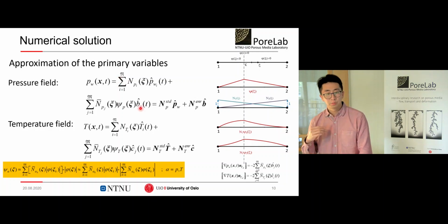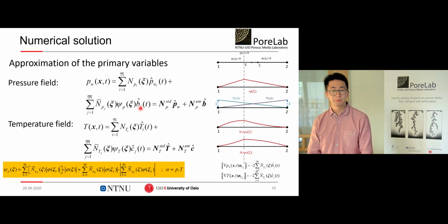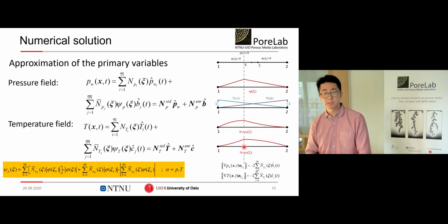So to approximate this, we need to add a continuous function with a discontinuous gradient. Here we use this modified level set function, as we see here, and the last two figures are for this enrichment function. And the same as the displacement field part, the enrichment function will vanish for elements not containing these discontinuities. And here is how to calculate this jump.